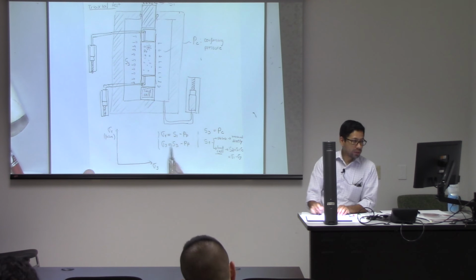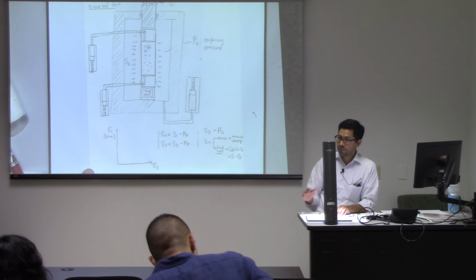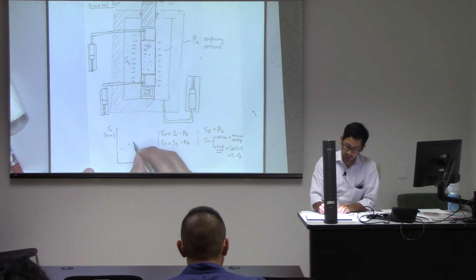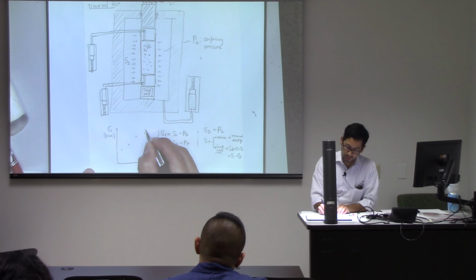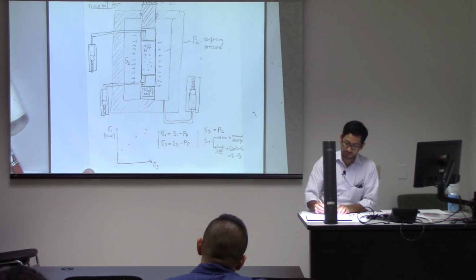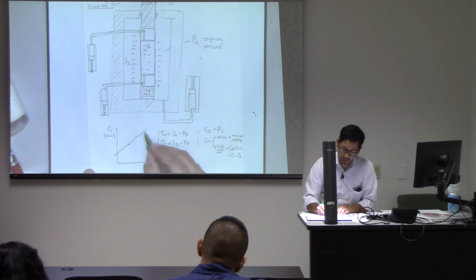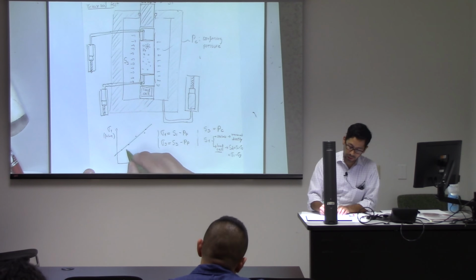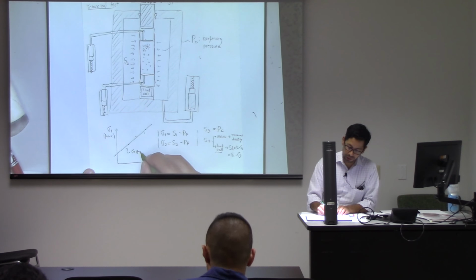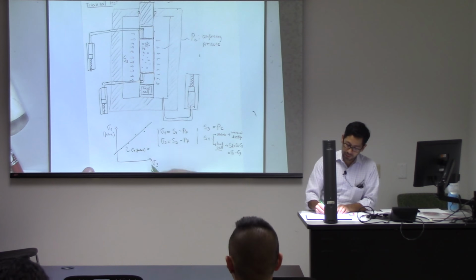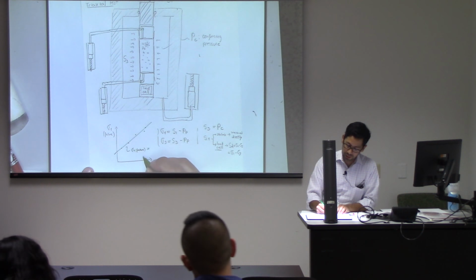And once you have all those values for different tests, for different samples, you can plot what the results of those are at different values of confinement, and then the line that joins that is going to tell you what is your equation of sigma 1 at failure, which, if this is a line, is going to depend on two constants.